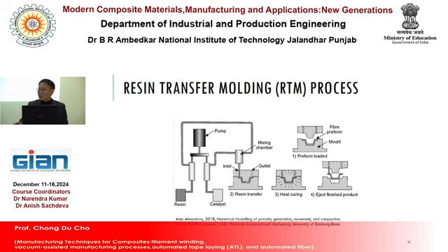That means that the molten resin has a viscosity, so it is very difficult to infiltrate into it. Okay? So that means you need a high pressure to inject the molten resin into it. Okay? And once it's filled, then heat curing is needed. Okay? And after heat curing, it's ejected. So you can get one product here.